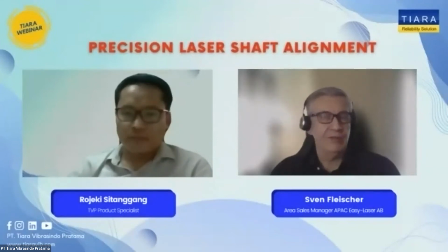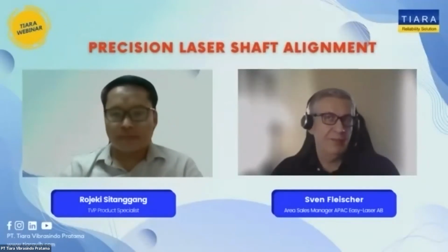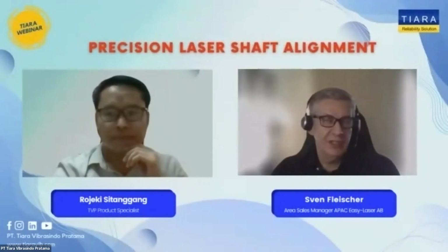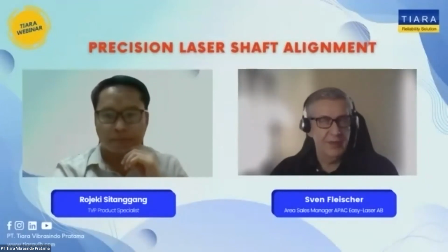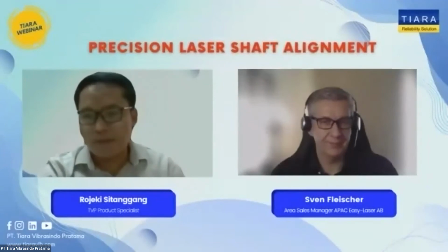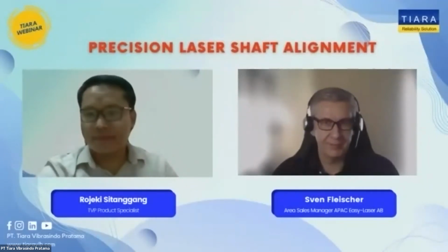So the way of measuring is different, but you can cross them with some coefficient to know how good or bad the older achieved result is versus the newer one. In general, dial gauge is not the same measurement principle as laser alignment, but you have the possibility to key in the related results of dial indicator alignment, reverse measurement technology, in a laser instrument, yes. Yeah, thank you, Sven.